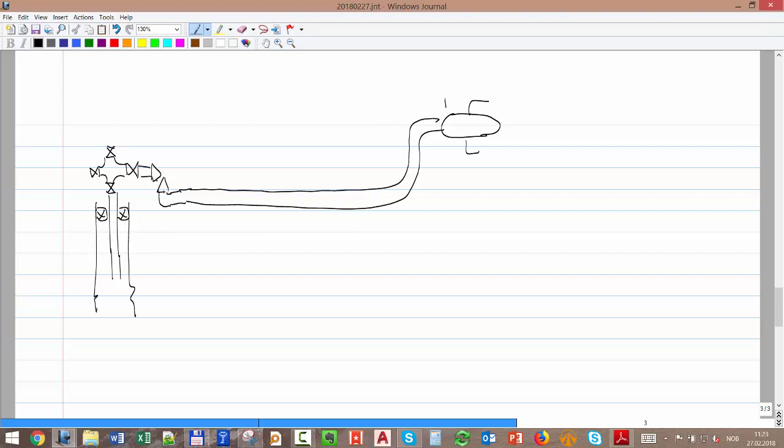Okay, and I'm going to move now. The point I'm going to choose is the separator, and I'm going to move countercurrent and calculate the pressure, let's say PDC, the pressure downstream of the choke. So how will it look? How will that pressure look versus rate? From the separator all the way to the DC versus Q oil, Q gas, whatever I'm producing in my system.